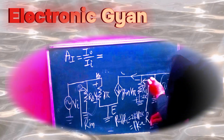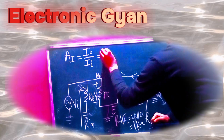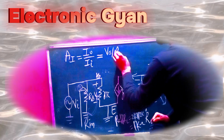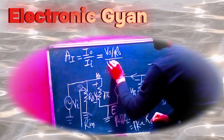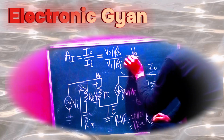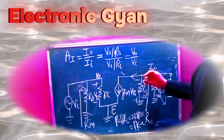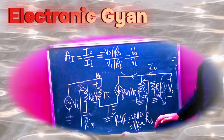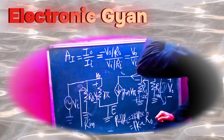If you see here, output is coming from this side. So I naught is equal to V0 by R naught, divided by input current, which is Vi by Ri. Current is coming like this, from the negative side, from the ground side. So it is negative: minus V0 by R naught is the current.